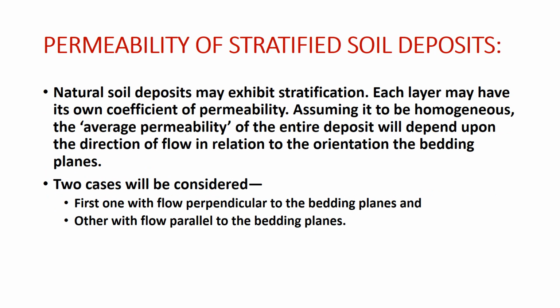Also, we can find out the permeability of stratified soil deposits, because in the site we don't get a single type of soil generally. So if there are a number of layers, or stratified soil, then we have to find out the permeability. Two cases can be considered. First, flow is perpendicular to the bedding planes, and the other, flow parallel to the bedding.